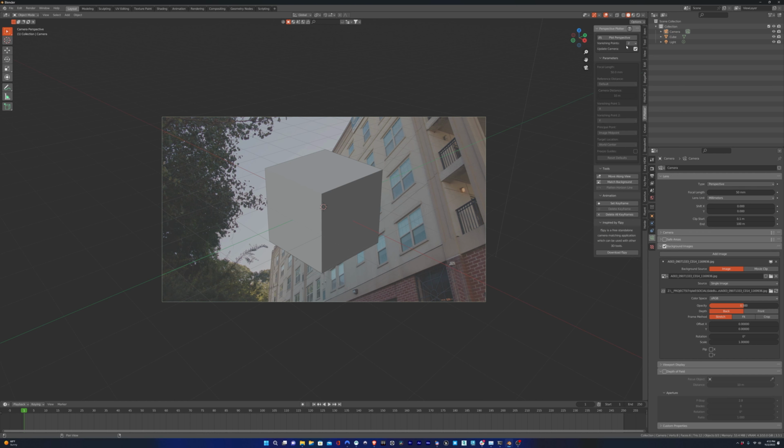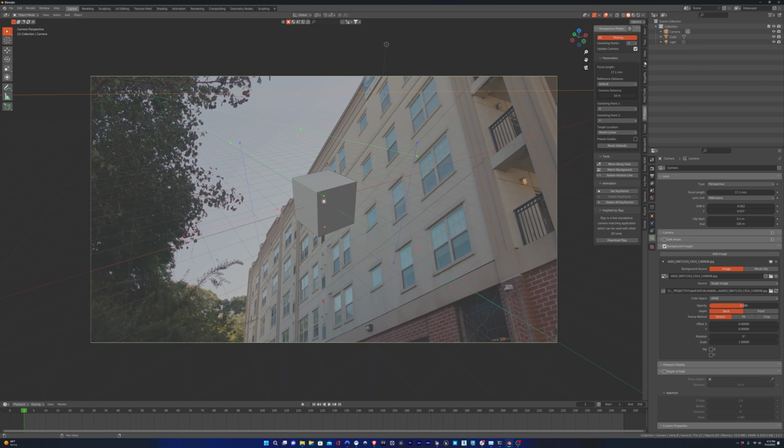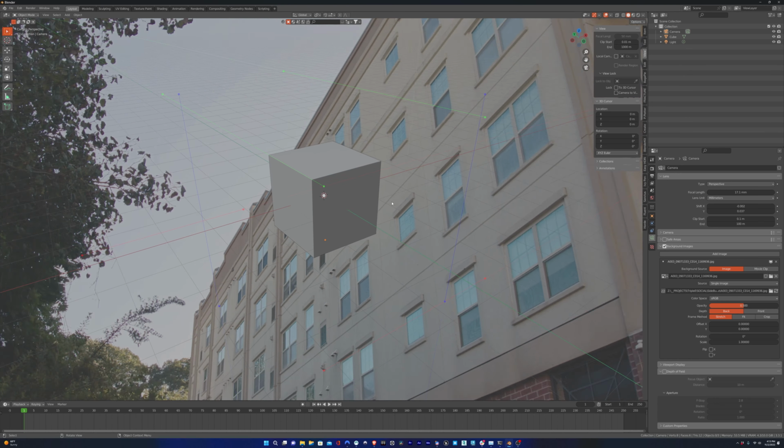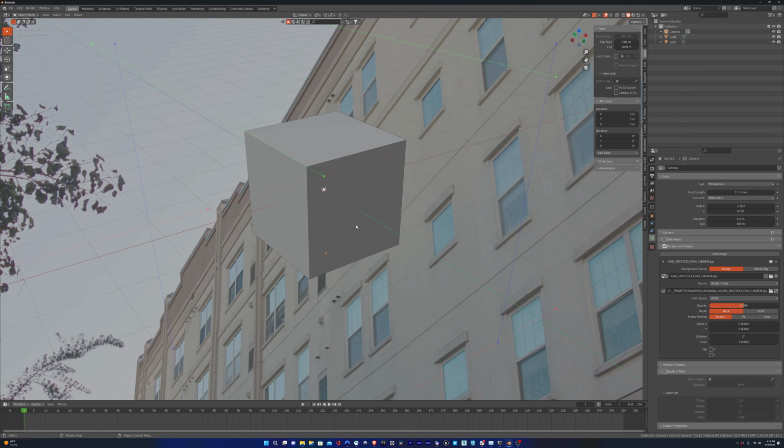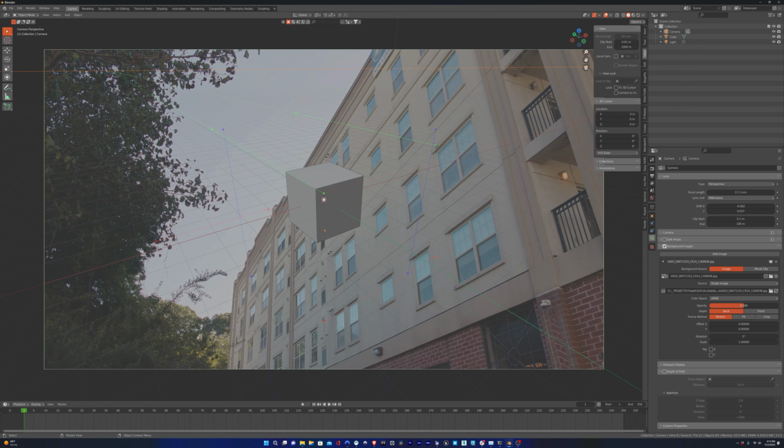Go to Perspective Plotter now and choose 3 vanishing points. So we have X, Y, and Z. Hit plot perspective. And just a little trick here. If we go into view, make sure camera to view is not selected so that we can zoom in and we're not actually changing the position of the camera. We're just zooming into the viewport. This is going to make plotting these lines a little bit easier.